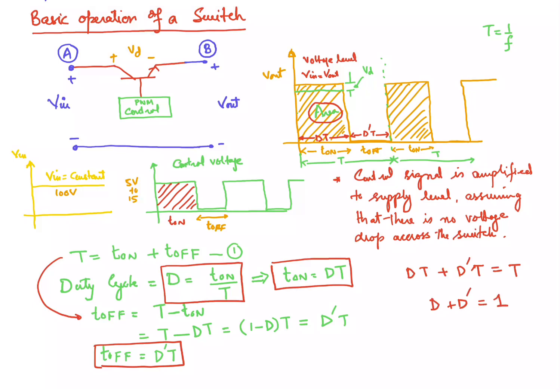Duty cycle cannot be more than 100% if you talk in terms of percentage. Over here, the switch is in the on state for, let's suppose, 60% of the total time, so the duty cycle is 60%, because T on is 60% of T. So the duty cycle is expressed in percentage as well, and it represents for how much time your switch was in the on state. The sum of the on and off time fractions will be equal to 1.